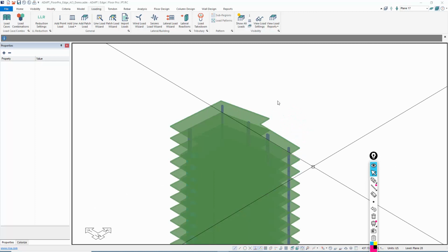Now these load cases ultimately have to make their way into load combinations in order to produce a result that might be meaningful, for example, for drift check or for design of a frame, diaphragm, or maybe the foundation or other vertical components like columns and walls.